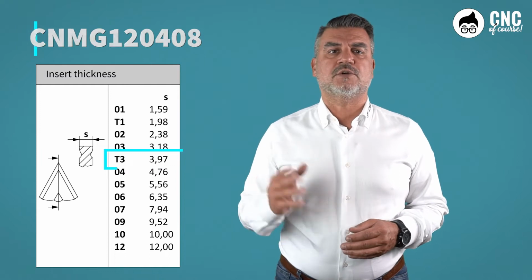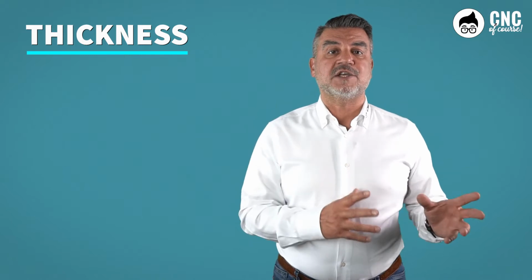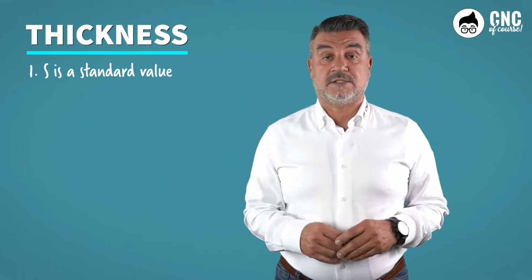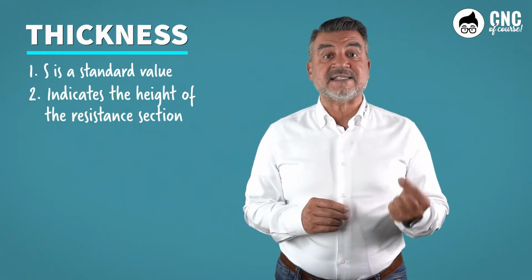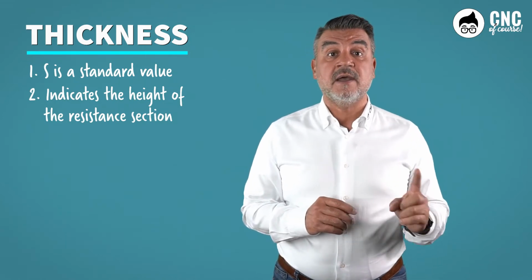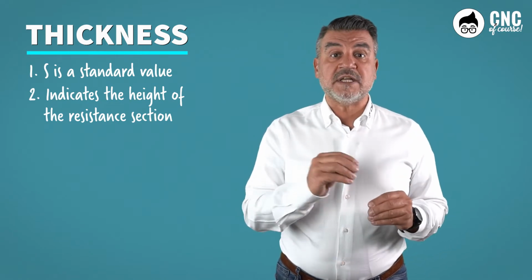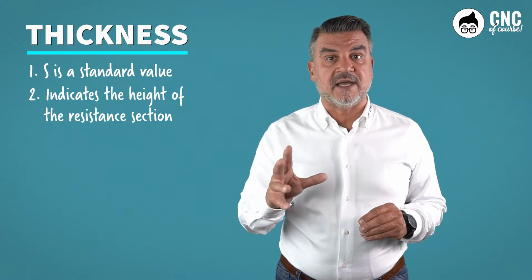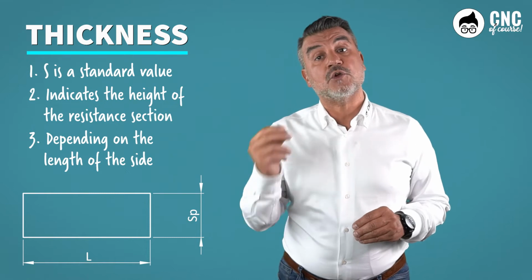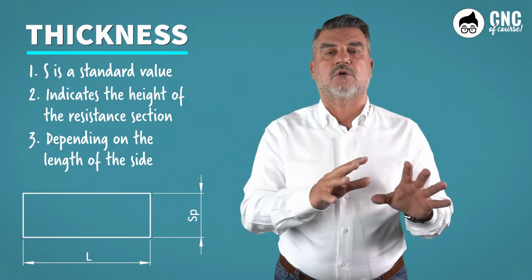Let us make a few considerations on the choice of thickness. Firstly, the thickness called by the ISO table with the letter S is a standard value. Second, the thickness indicates the height of the resistance section. Therefore, the greater the resistance section, the greater the strength of the insert. Third, the thickness of the insert, so its strong section, is a function of the length of the side. The longer the side, the thicker the insert, the stronger the insert. And these 2 parameters will always be related.